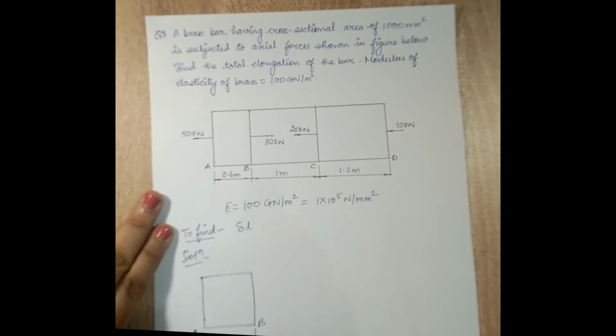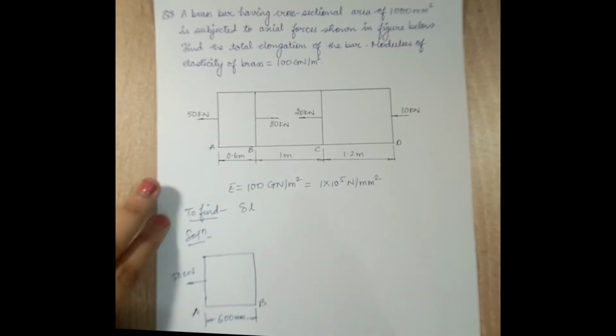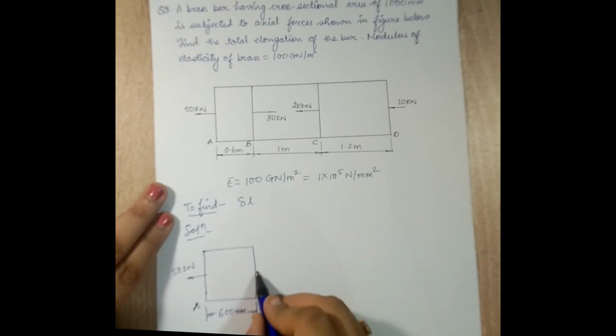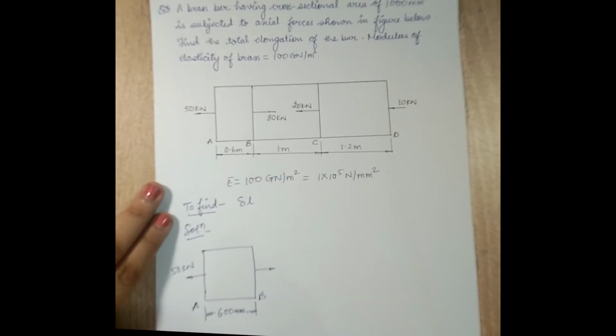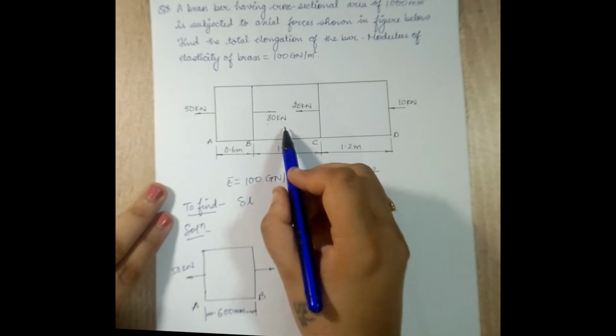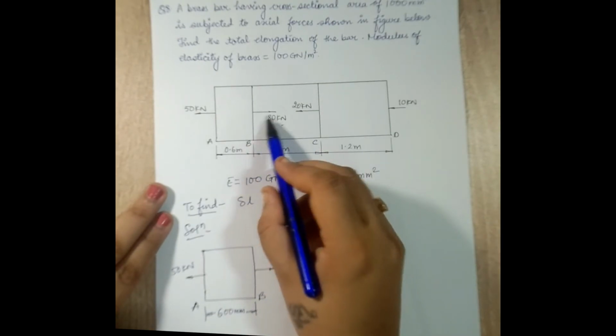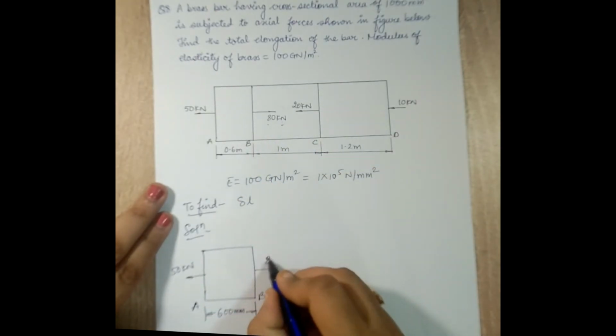I'm going to take everything in mm. To the left, I see the load is 50 kilonewton. Obviously, to the right, it has to be 50 kilonewton. I will just check once, and the direction obviously has to be tensile. If you recollect the derivation that I have made, we'll still do it again. 80 kilonewton at junction B is of pull type, so this will be positive 80.